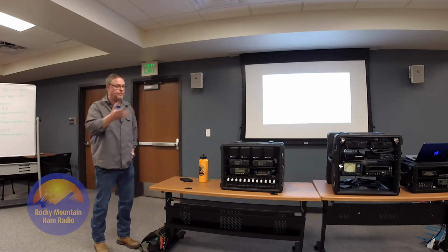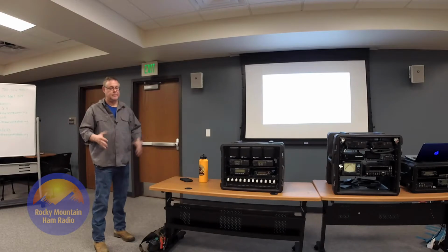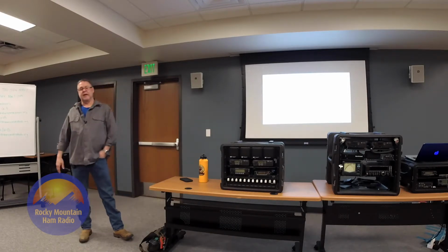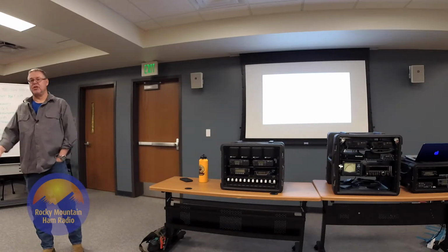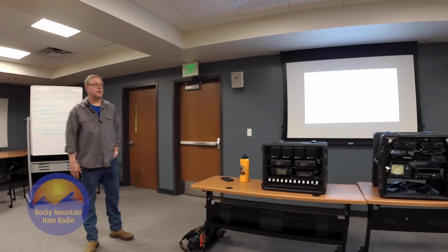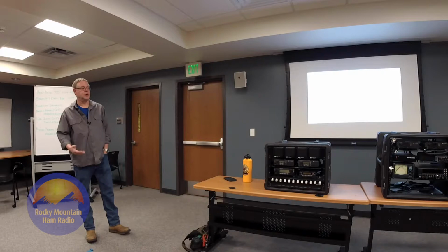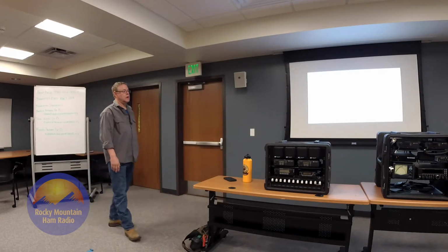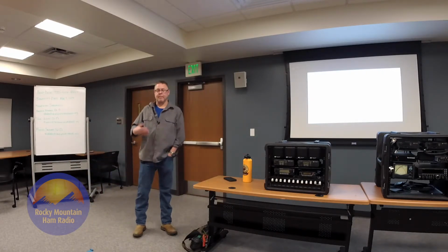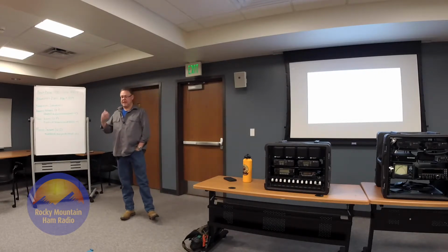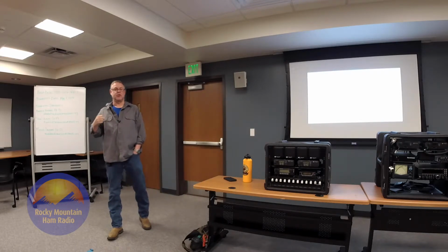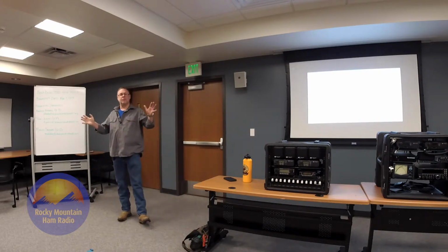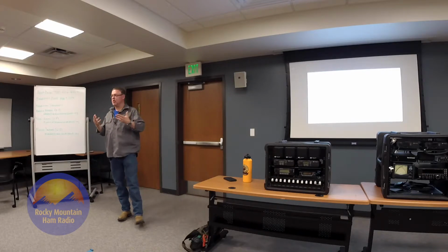And they all come in the battery you're familiar with, the big rectangular square battery with the 2 posts on top. AGMs are sealed. They're better known in the marine, solar and wind turbine world, where they're maintenance free and have deep cycle capacity, meaning they don't just give a burst of high amperage to start a car or an engine, and then they're done until they're recharged.